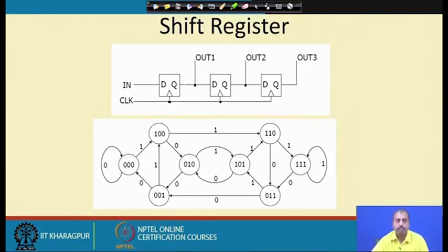So, this is the other way. From the circuit we can come to the finite state machine. Here no other combinational logic will be necessary, because if you simplify this particular machine for the state transition function and output function, you will find that it gives rise to functions like Q2 equal to D2 equal to Q1, D1, D3 equal to Q2, like that. So, it will come in a simple fashion. That is why we do not show the circuit separately, but this is nothing but this connection.